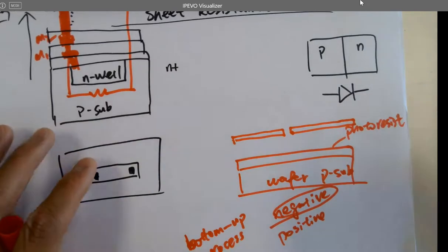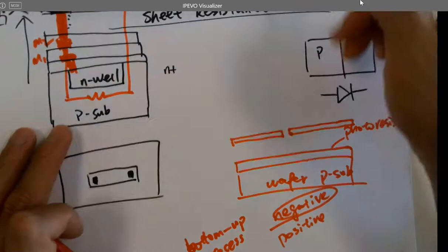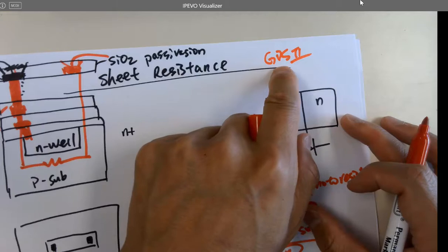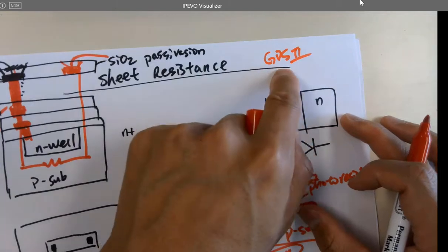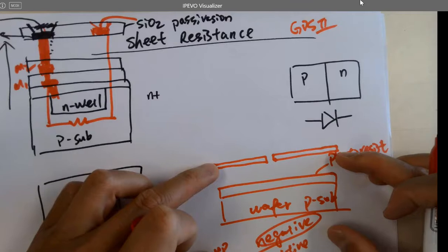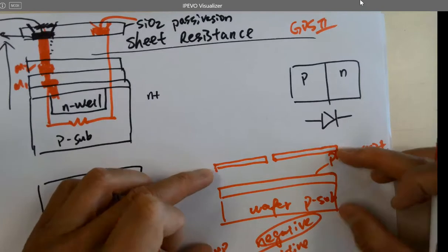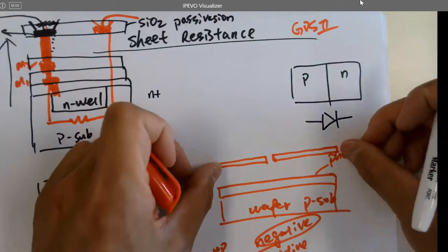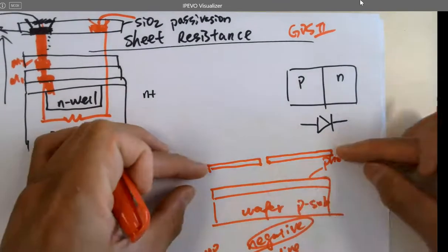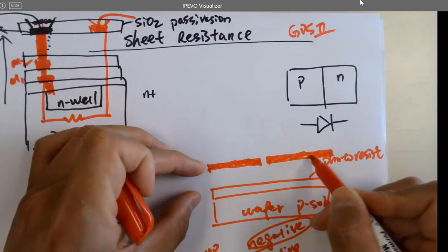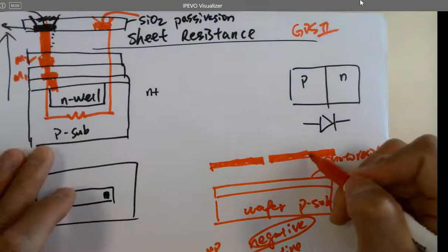Yeah, that's what you're doing right now, right? In Cadence. It's called a GDS2 file. That's the final file you are going to submit to TSMC for fabrication. And eventually these GDS2 files will be printed on either glass or plastic films as different layers of masks. And that's it. So they will apply the first layer of mask here. Definitely they will make contact with each other, so the light is not going anywhere else. But I'm just putting it here, as you know, they physically place a mask over here. So these are ink. The ink usually is chrome. That kind of material is opaque, so the light cannot go through.